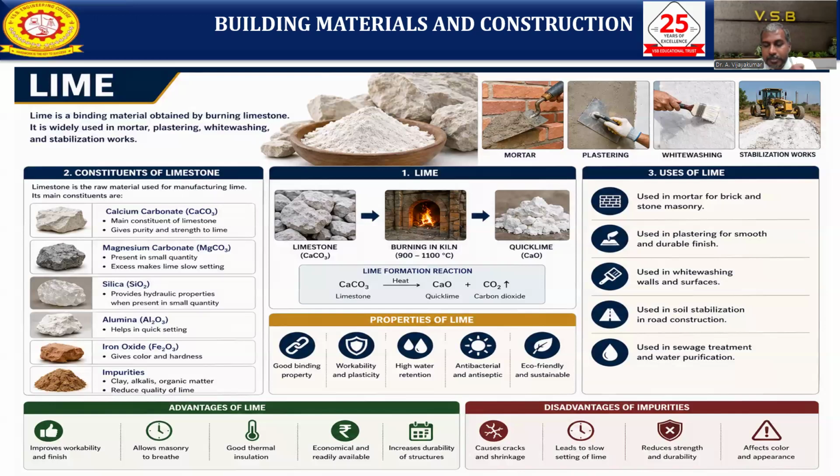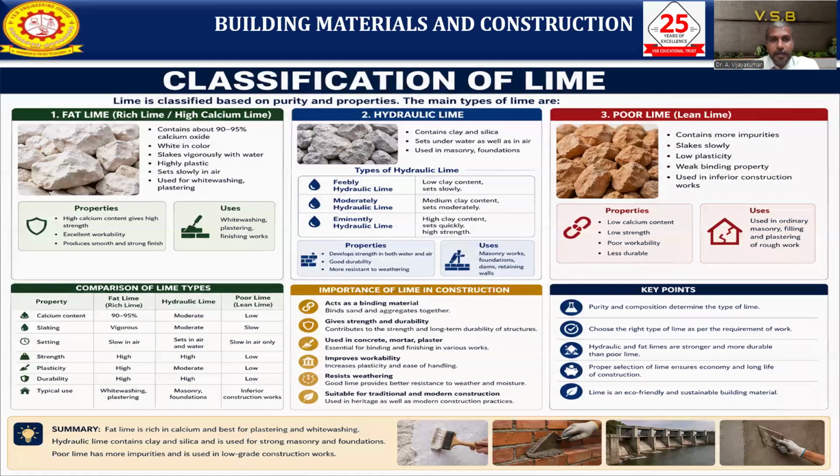Coming to the disadvantages, the lime will expand, and cracks and shrinkage will occur. The setting time is very slow compared to cement, which reduces the strength and durability. It can also affect the color as well as the appearance. These are the common disadvantages of impurities in lime.